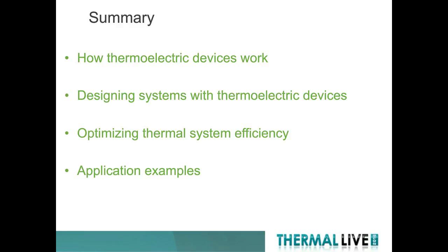The next question is from Kiran from Molex. How suitable are TECs in automotive applications? Jesse, do you want to comment on that? Very suitable for automotive applications. They're very robust if properly installed and properly integrated into the system. They can be very effective at providing cooling or heating in automotive applications. Not typically to, say, cool an engine block, but perhaps a battery pack or a person. They're absolutely applicable.